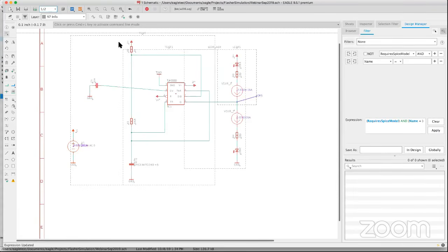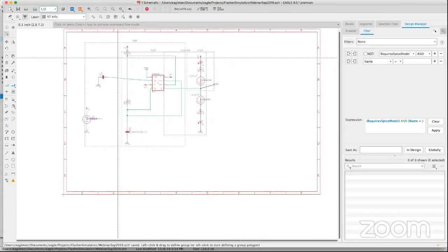Yeah, we have a question: can you export a group of components to a new schematic? That's Daniel's question. You want to answer that one live? I think I can. So you mean to a different design? Yeah, he wants to take a group of components and put them in a new schematic. So basically, it's group copy paste in a sense. That's one way of doing it. One way, you have design blocks also. Or you could just go ahead and define what's called a design block.